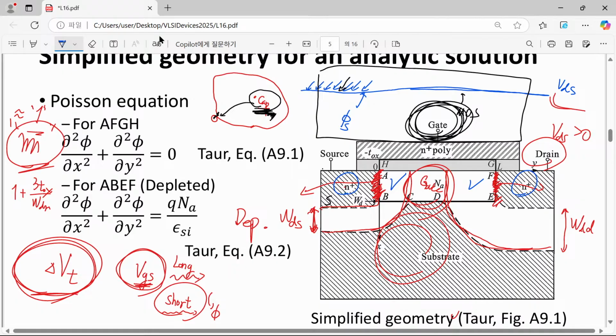No, it's not. Their behavior is actually governed by the collaboration between source and gate, or drain and gate, because this part is quite close to the drain and quite close to the gate. So this part is governed by these two different terminals.